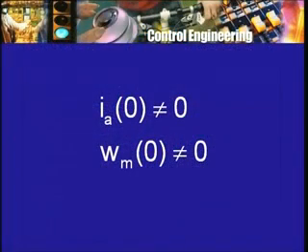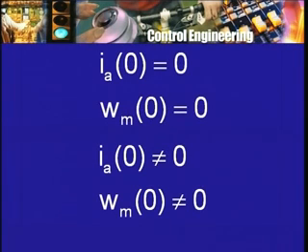Now, in that case, we start our investigation from this moment when these changes are taking place. So we will say that that will be our t equal to 0. That will be our initial instant of time, and we will look at the behavior from there onwards or thereafter. And therefore, then the initial values will not be 0, because the motor was already running, the armature already had some current. So the armature current at that moment of time, of course, we may choose to call that moment of time 0 once again, because it is a new investigation. So then Ia 0 may not be 0, and of course the motor was running, so omega m 0 is also not 0. So the initial values may not be 0, they may both be non-zero. But as a special case, when the motor was at rest and the circuit was not connected electrically, the armature current and the motor speed were 0, and therefore the initial values will be 0.